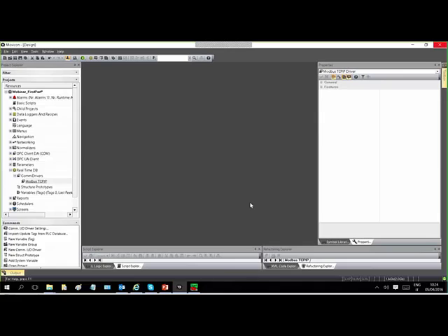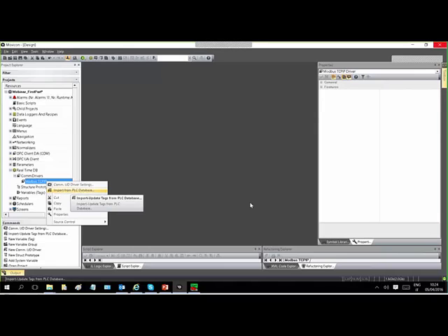Now, the next step could be to insert your variables. It's important to insert your variables. You can proceed manually, but it's not the good step. All our drivers offer the possibility to import the tags directly from the PLC. It's a good engineering rule, also in my previous experience. You normally create the logic and create a sort of folder where you decide which tag to share with the SCADA system.